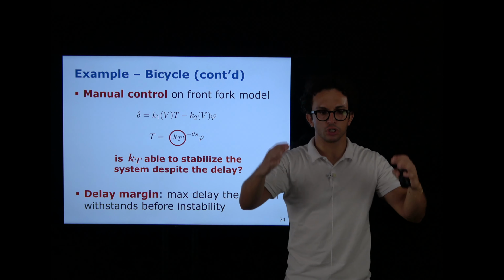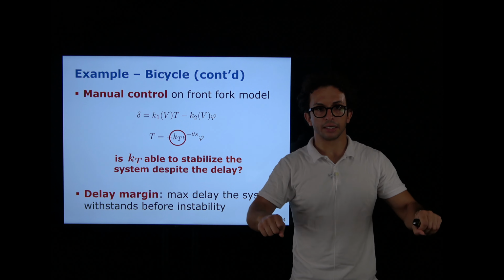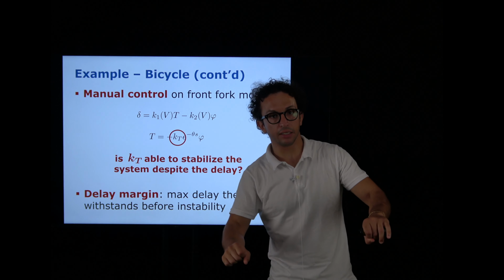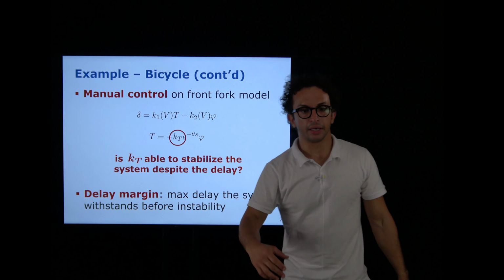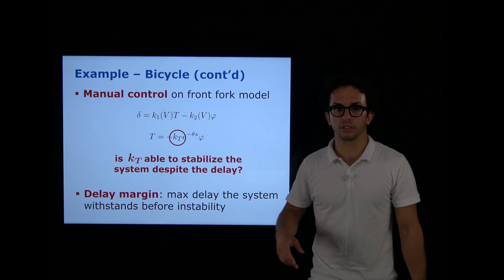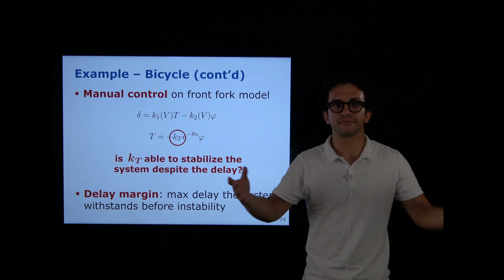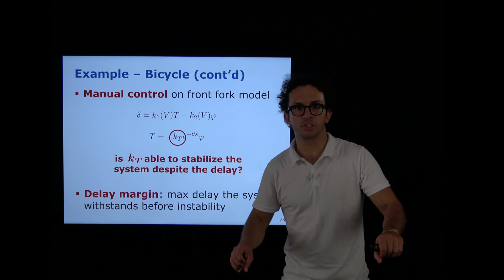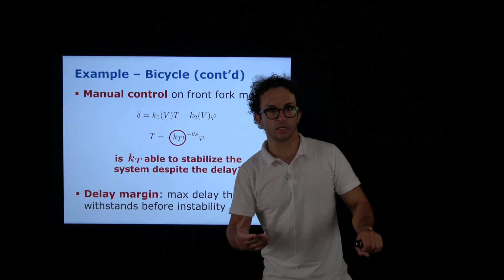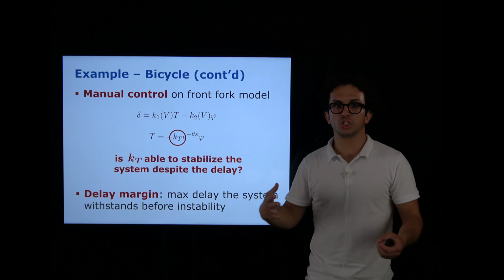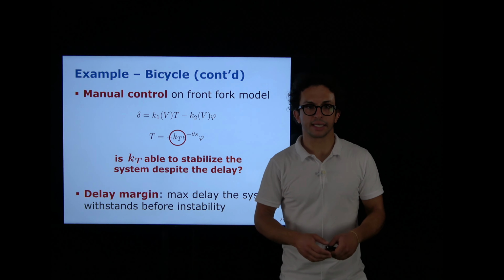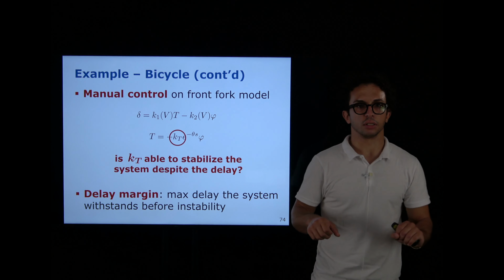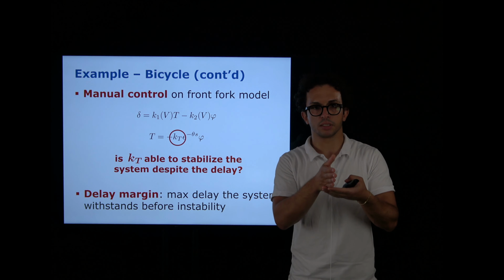And this you can actually imagine. Imagine that you are on a bike, the bike is leaning, and you have to think fast. Okay, I'm leaning a lot, I need to steer. If the neuromuscular delay that we're considering in this case is like 5 seconds, then you fall down because you're too slow in deciding to steer in the opposite direction of leaning. While if the decision process takes 0.1 second, you say, oh, I'm leaning, I just adjust it a bit. Oh, I'm leaning again, I adjust it a bit. Then you will be able to actually keep stability.